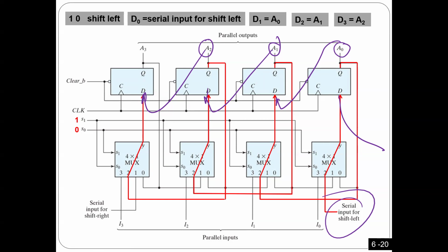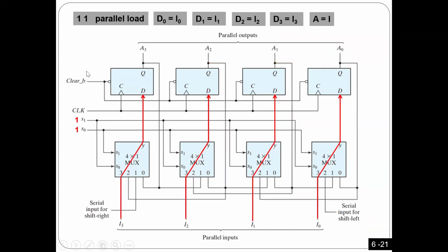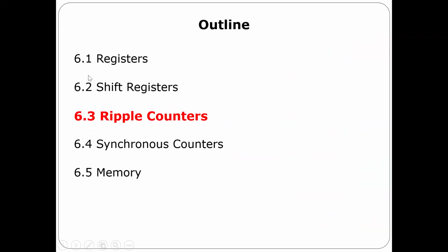And now, sometimes you have a chip. This chip has a universal register. We call it a universal register because you can make it shift right, shift left, or do a parallel load. So in this case, regarding your question, I can make it parallel load, and then I shift. That's what I'm saying. This way, I can convert parallel to serial. Anyway, okay, guys, any questions?